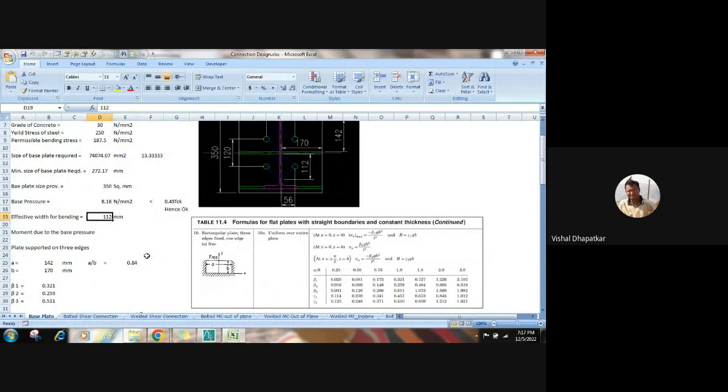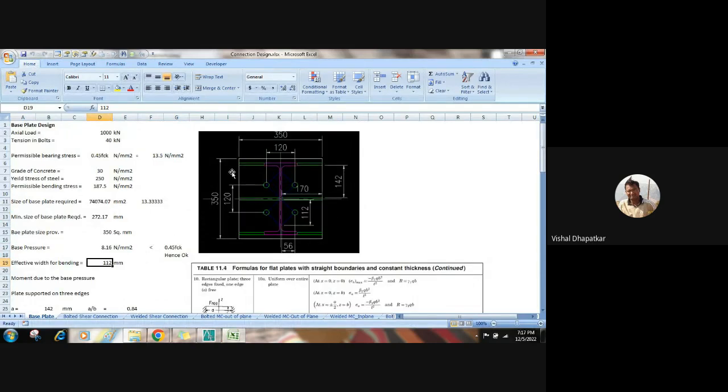Okay. So now let's start. First we got the pressure. Now the base plate will be designed for the two forces, right? So we got the plan size of the base plate. Now what we want is the thickness of the base plate. How thick shall the base plate be for the given loading? That will be governed by two factors. One is the bearing pressure acting from the bottom of the base plate, and the second is the tension in these anchor bolts, right?